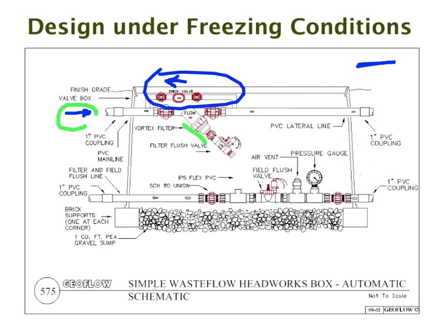It will flow through the filter and out to the field. And then here, coming back from the field, we've got the normal flush back from the field, and this is the field flush valve. So when you want to drain, you just open this flush valve and there's nothing stopping the flow going back.